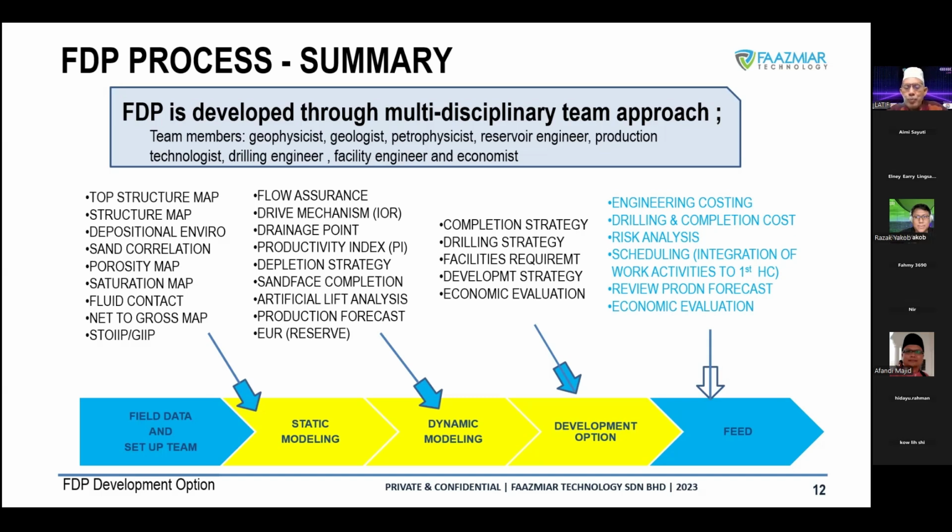So, sand face completion. Normally when talking about the sand face, we have the casing, we have the perforation, and then the wellbore radius that is going to be affected by the skin. We're talking about how the production comes from a long distance through the field. Imagine we have one well with oil coming up from a 1 kilometer radius, for example. It all comes up with dirt and fines, and then it will cause plugging later on. So what's going to be your solution to solve the issue?